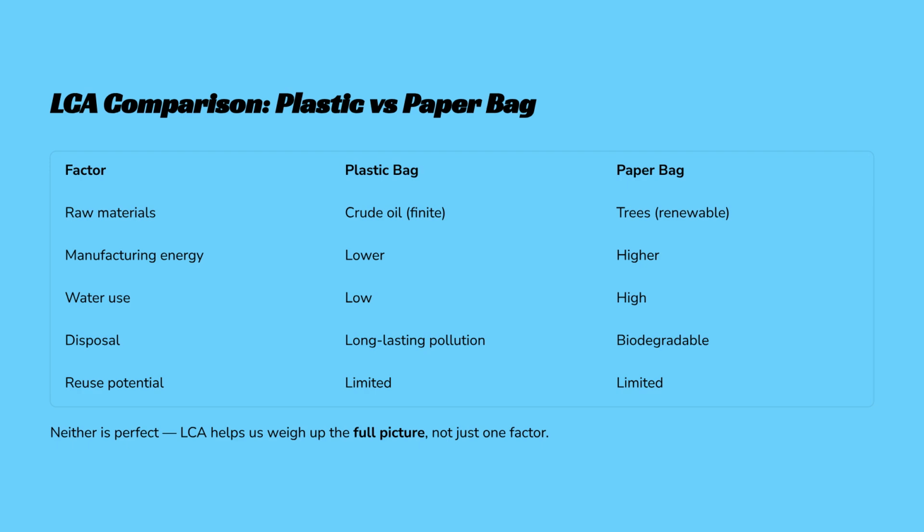Comparing plastic and paper bags shows that neither is perfect. Plastic uses finite raw materials but less manufacturing energy and water. Paper uses renewable raw materials but more energy and water. LCA helps us weigh the full picture, not just one factor.